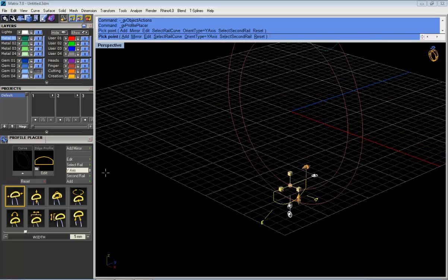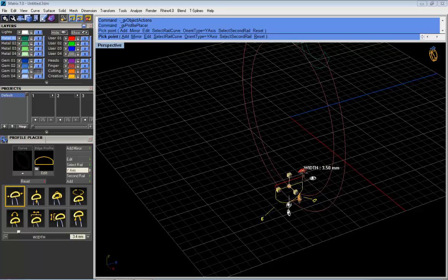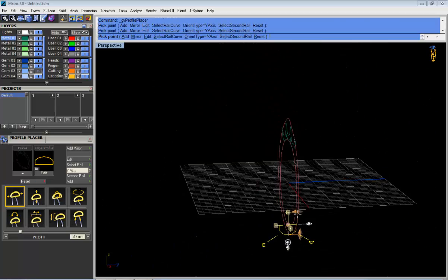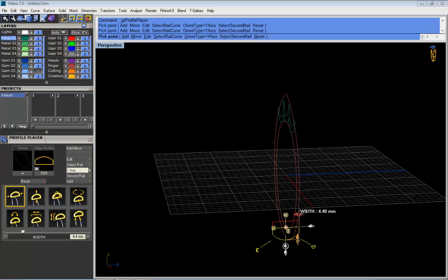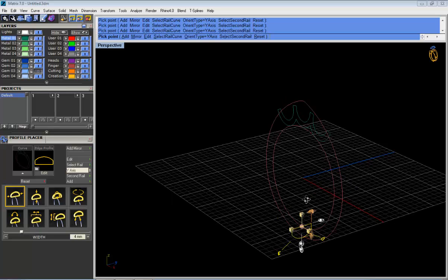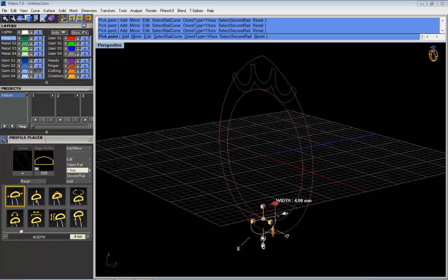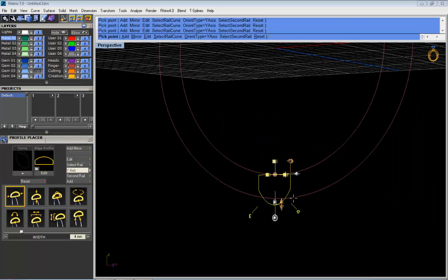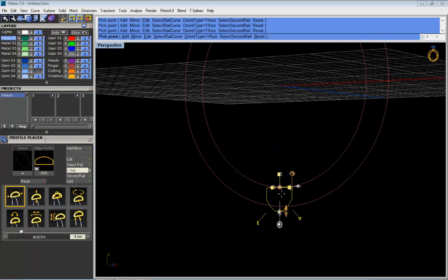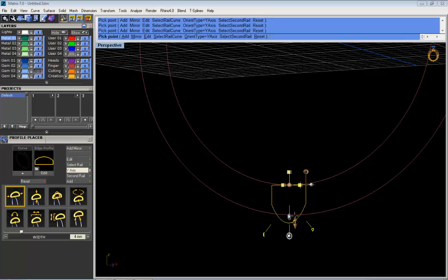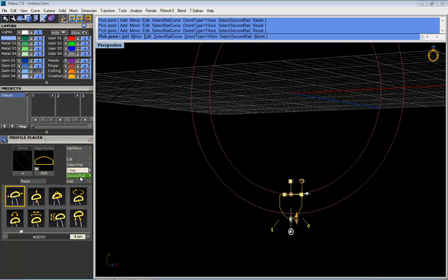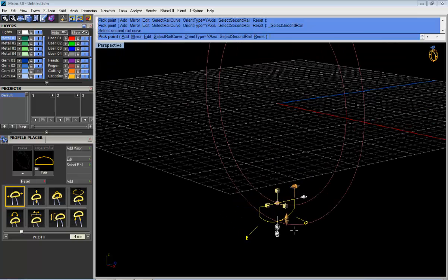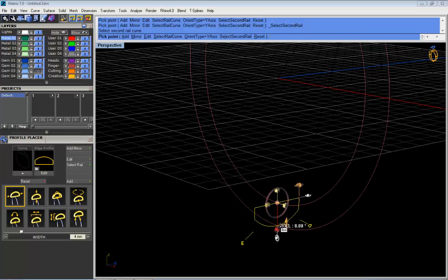Anyway, I'm gonna select the thickness, sorry, the width, about, the gems are 4 mil, so yeah, I'm gonna make it quite straight, quite 4 mil as well. Okay, now width is alright, but height is not, basically because you see it goes further, the outside one. We want it to be exactly the same height as we have from the ring rail to the outside. To do so, we need to select here second rail, and now basically select the outside, which is this one. You see, so now it really fits from the ring rail to the outside ring rail.